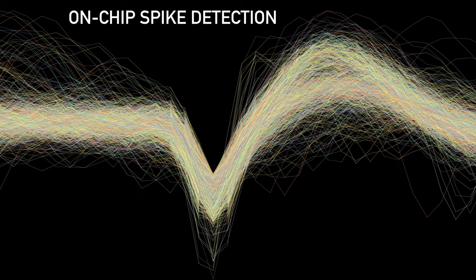Currently, there are several different methods for detecting spikes, such as thresholding, or more sophisticated methods such as principal component analysis. At Neuralink, one of the robust ways that we came up with is by directly characterizing the shape. And it's worth noting that this is different than template matching in that it gives us more information in a general way. In certain cases, we can actually identify different neurons from the same electrode based on their shapes.